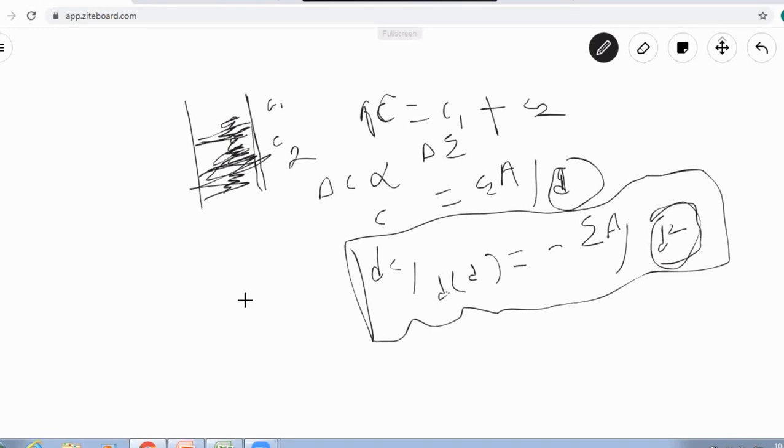The first characteristic you have seen is that there is a linear relationship between capacitance and displacement in the case of the overlapping area and the dielectric medium. But when you vary the distance between these two plates and the distance increases, what will happen? The capacitance value will decrease. That is the effect. So from this equation, we can say that it shows a non-linear relationship.